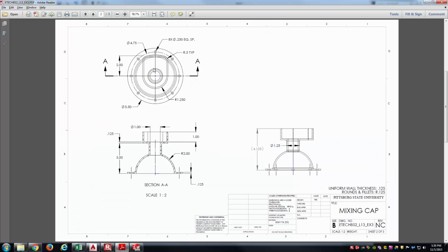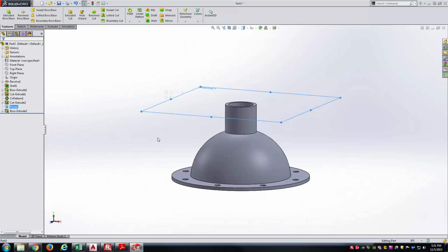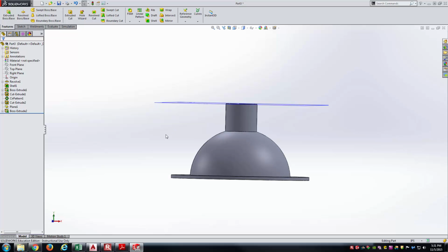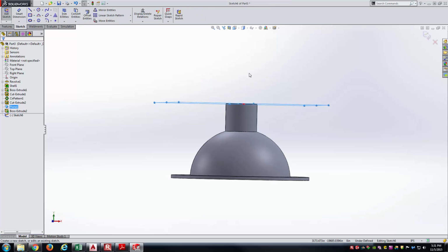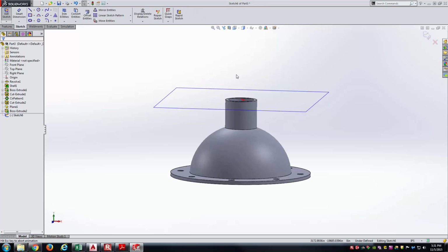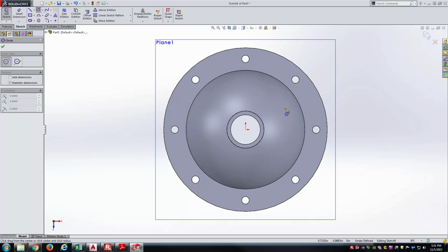And now we just have this top portion above. And so the top portion, you can see it's just a half circle essentially, a few straight lines connected by some rounds in here. And so let's go ahead and draw the base portion of that first. Then we can use something like offset to draw the vertical walls. And so that base portion, I should be able to sketch the profile on this plane 1 that I've created.